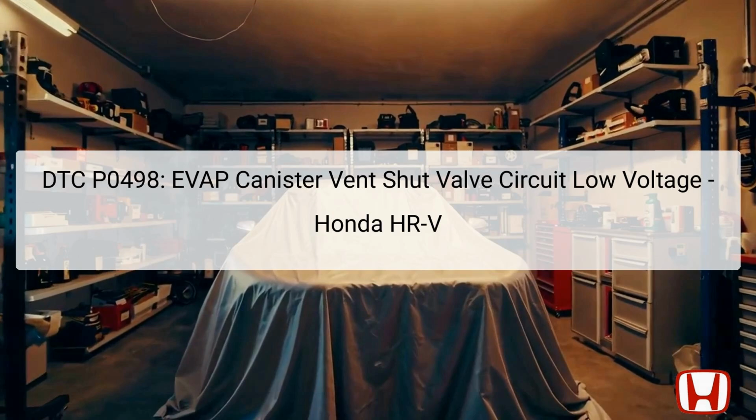The Diagnostic Trouble Code DTC P0498 refers to an issue within the evaporative emission control system, specifically indicating a low voltage in the EVAP canister vent shut valve circuit. This valve is integral for controlling the flow of fuel vapors from the fuel tank to the charcoal canister to prevent them from escaping into the atmosphere. Its location is under the vehicle, near the rear fuel tank area, where it is connected to the EVAP system.